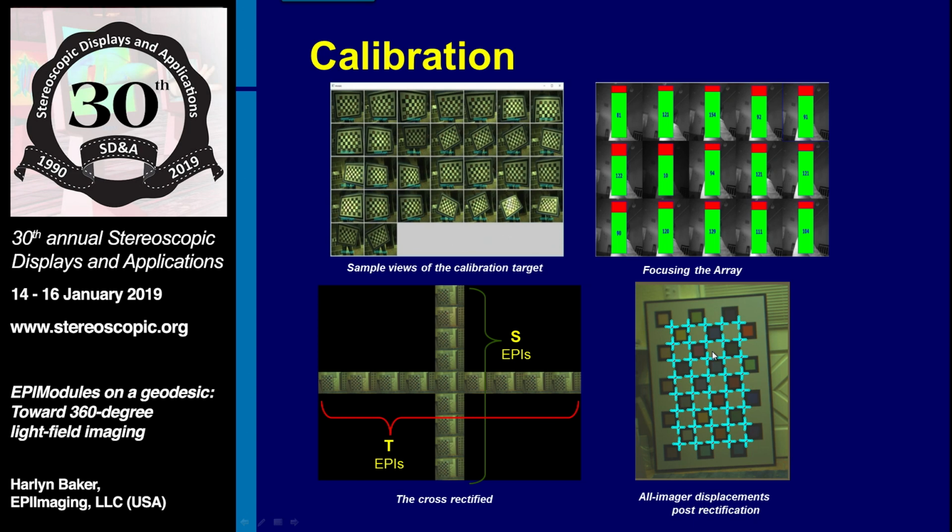Calibration, we have many ways of viewing the results from this. This shows here what the individual cameras see after you rectify them, but before you apply our final refinement process to it. So the centers of projection are kind of bouncing around a bit, and when the final refinement works, everything lines up. So the centers of projections of the cameras lined up look much like they do in the module itself. They're displaced here by that baseline. So we can see that the cameras are looking good, and in the earlier case, they were kind of screwy. So the calibration is something we need to have good tools for assessing, not just numbers, but looking at what